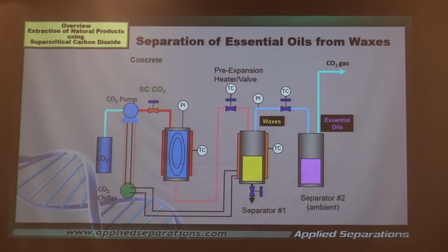We've talked most of the time with supercritical by changing the solvating power. But there's nothing that says that you can't bring it all the way back to a liquid. And then there are some things that are not soluble in some liquids. In the case of waxes, they are not soluble in liquid CO2. So they typically then will fall out of solution, and you've done the separation this way. You've fractionated them.